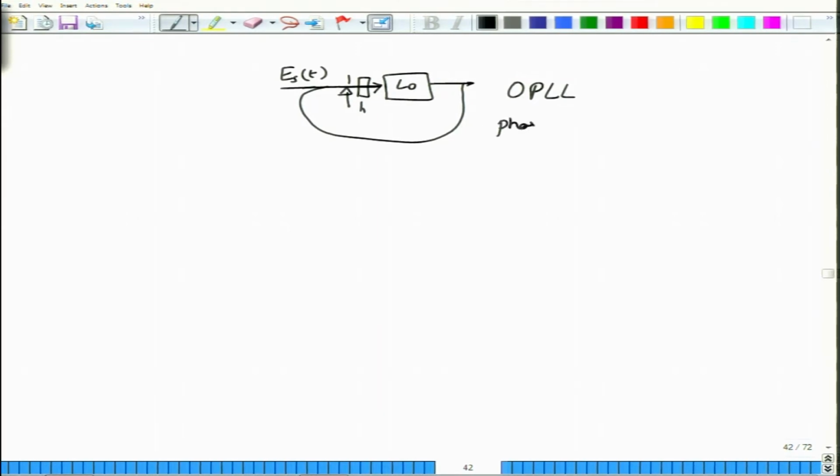It is optical because this is being done using lasers. A phase locked loop is a very common device in RF systems. You can get very nice, high performance PLLs with very narrow bandwidths, and you can use these PLLs to synthesize whatever frequencies you want. Unfortunately, in an optical phase locked loop, the major problem is that you are dealing with two different lasers. One of them happens to be at a remote site.